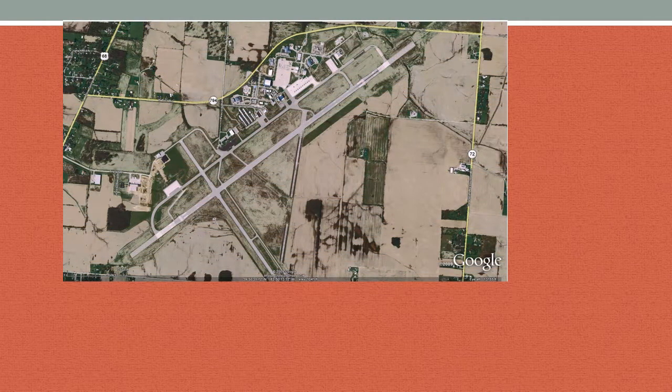A civil scale for large works is, let's say, 1 inch equals 300 feet. But if you take a situation like this, which is the Springfield, Ohio airport with a 9,000-foot runway with 1,000-foot overruns, fitting it on a page... So at that scale, a 9,000-foot runway would be 30 inches long, but the width of the runway might only be a 1/2 inch wide. And so a lot of items would be too small to show in detail.